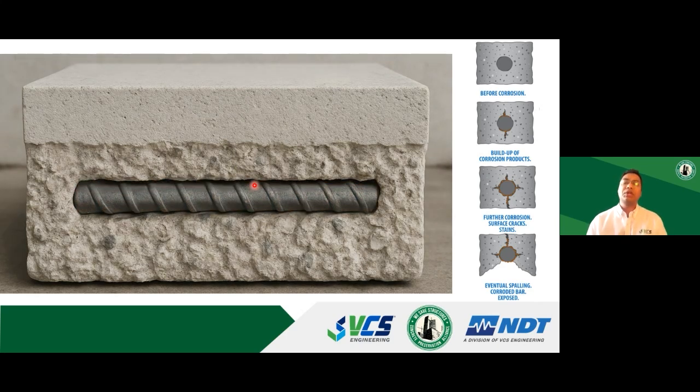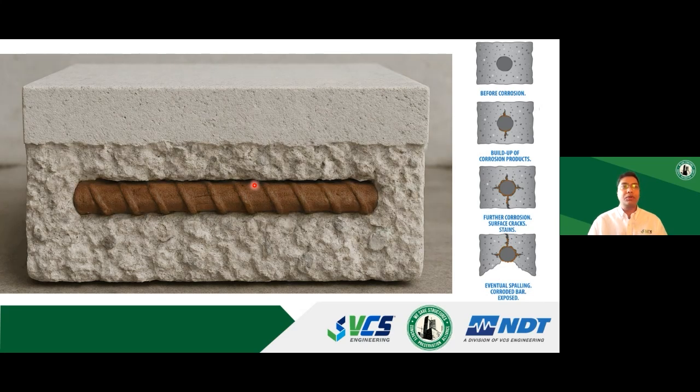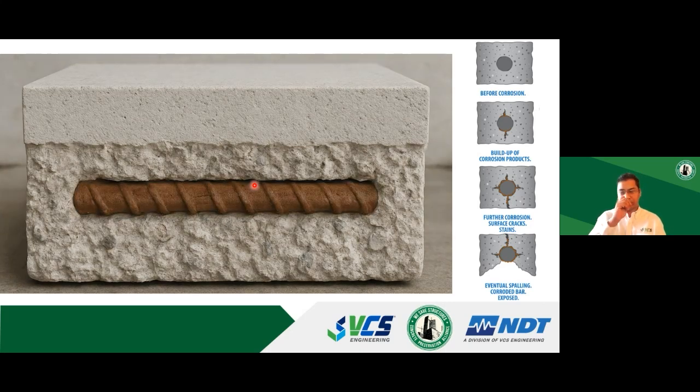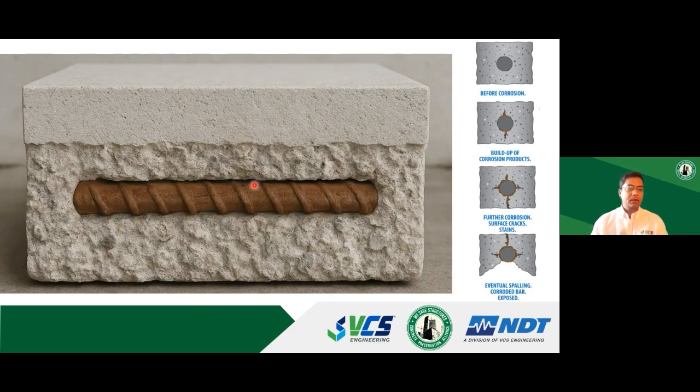But with post-tensioning structures, the rust product forming on your strands is completely encased in the metal duct for bonded post-tensioning, or for unbonded post-tensioning, it can be completely encased by the plastic sheathing around the steel. So you might not have enough warning signs of failure of the structure. That is how I tend to think about distinguishing between a conventionally reinforced structure and a post-tension or pre-tension structure. Yeah, because we run into all those conditions.